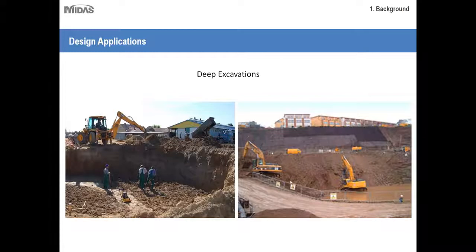There's a certain amount of fencing that's been created. The slopes are there, but as you can see, it's not particularly safe to walk along this area yet, just because the slope's still being constructed. And as you can see, the excavation lining is done, with the slope. The reason this is done is that it's not logical or very safe to have the excavation dug in at a 90-degree angle. It'd be very dangerous. If that were to fail, there'd be large amounts of soil falling, which would take a long time to fix or clean up.